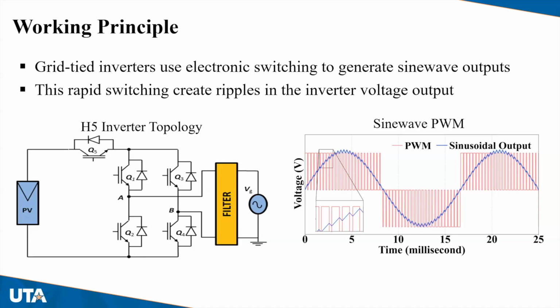That is what you can do, but that's not enough, because it's alternating current, but it's not a sine wave. The way they create a sine wave is they do a lot of electronic switching, and instead of getting a real sine wave, what they get is a zigzag sine wave. That is actually the best they can do. They use a pulse width modulation technique, where when you want to go up the sine wave, you keep the circuit on for more time and off for less time, and when you're going down, you do the opposite. This is how you get the sine wave.